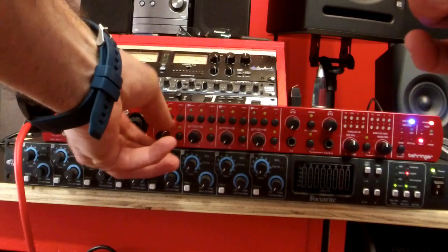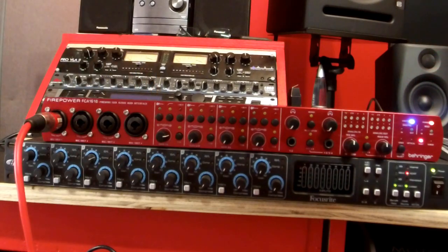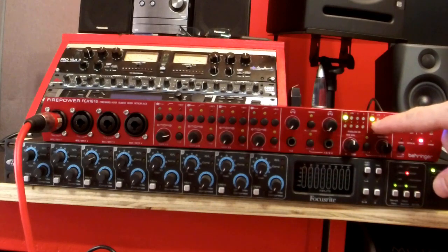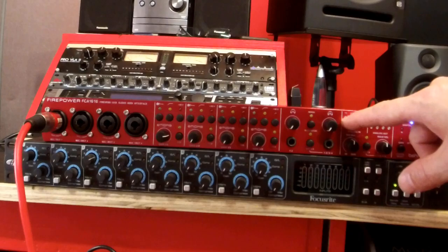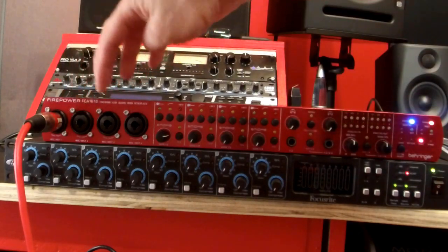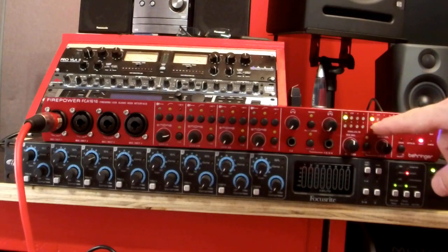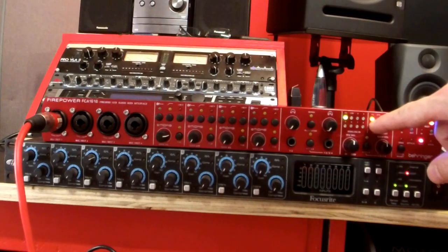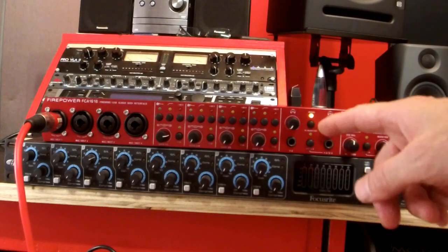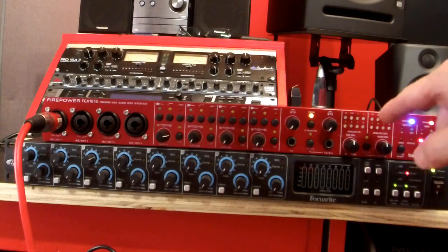I'm just going to turn the volume up, and we should be able to see signals at the input as analog, and we can also see the signal at the output. Now you will see because it's pairs, left right, that's why we are only seeing the output to the left, and that's when we can press the mono button. Now we have our signal going out to both channels.